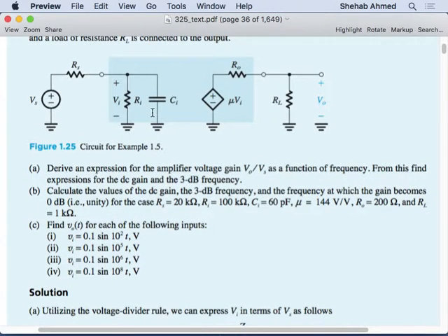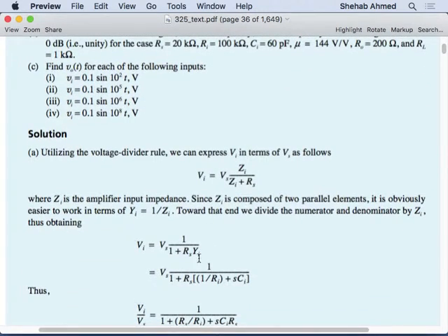To add two impedances in parallel, 1 over Z equivalent of two components in parallel is 1 over Z1 plus 1 over Z2. So you can add those, and then instead of representing them as impedances, it's nice to just flip that and represent that as an admittance. That's what we discussed last time. So we divided by what? What did we do? We divide by Zi, right? We said if we divide by Zi,